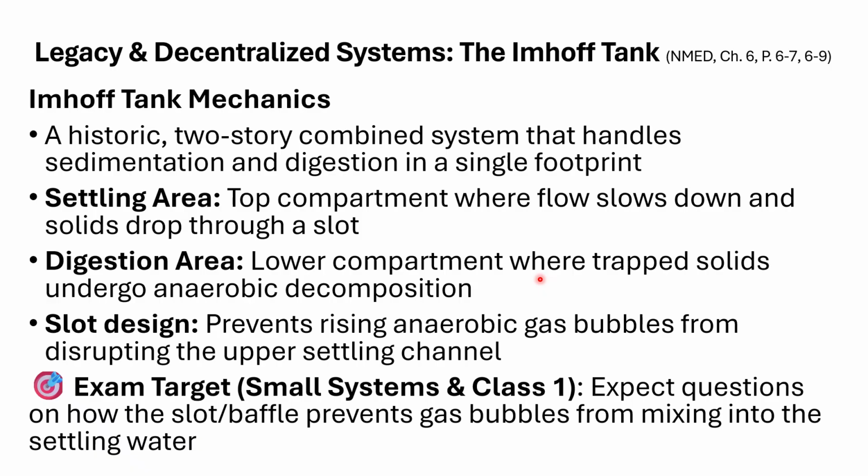The Imhoff tank is going to have an anaerobic, or lack of oxygen, decomposition. Okay, and we've got a slot in there, and just like with the boot seal on the earlier combined unit, that slot's designed so that those anaerobic gas bubbles are not going to go to the upper settling chamber and create problems there.